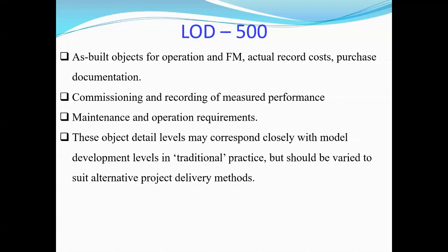Secondly, it is for alteration and addition. If you want to do any structural alteration in the building, you already have all the information, so you can see the requirements and whether you are able to do the alteration or not. Sometimes you want a change of use. Then you can check the loading, whether the original design already has an allowance for this loading or not. If it doesn't, you can decide whether to do strengthening or not. So all this information is already available, and your work is easy.